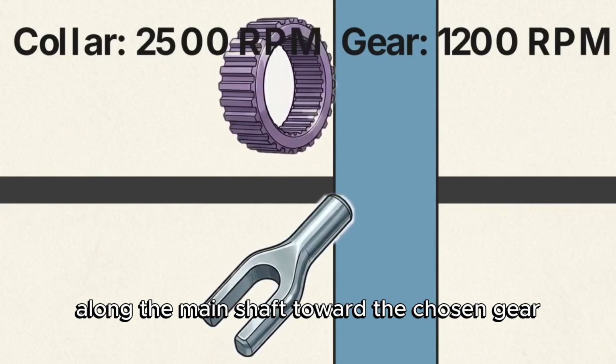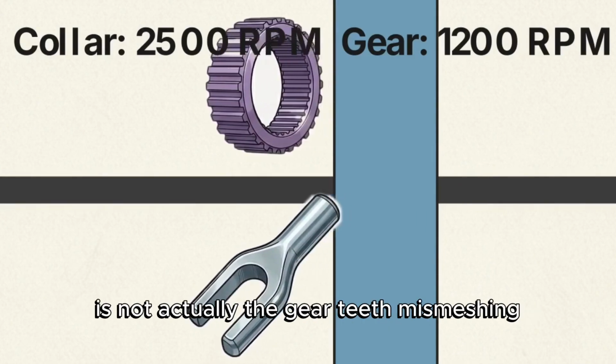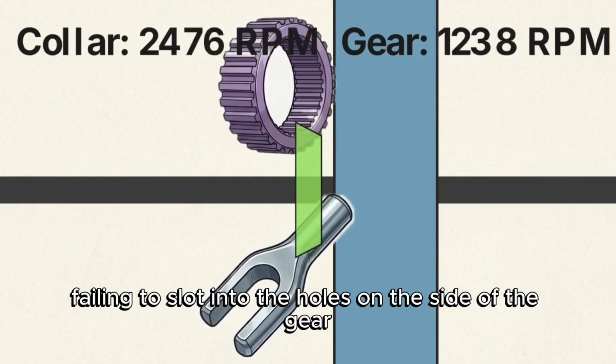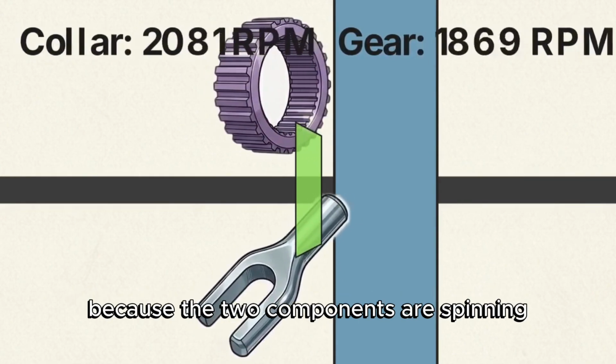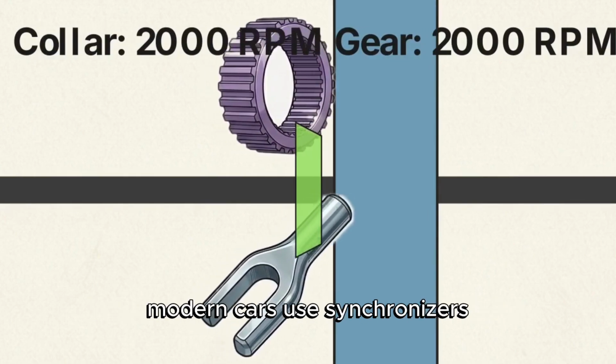The sound of grinding gears is not actually the gear teeth mismeshing. It is the sound of the dog teeth on the outside of this collar failing to slot into the holes on the side of the gear, because the two components are spinning at different speeds. To prevent this, modern cars use synchronizers.